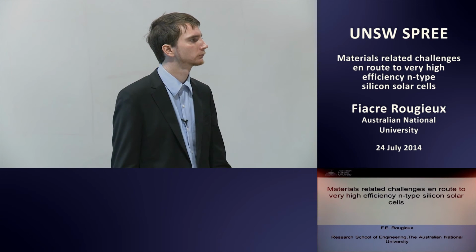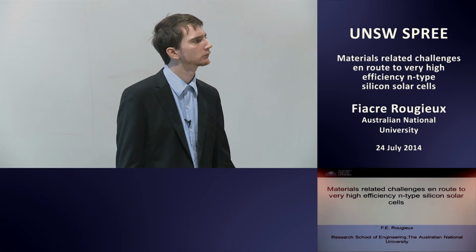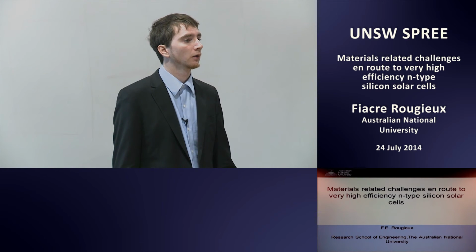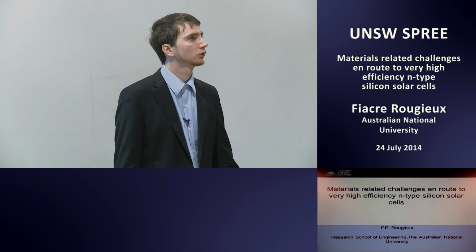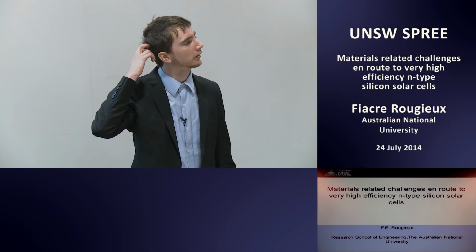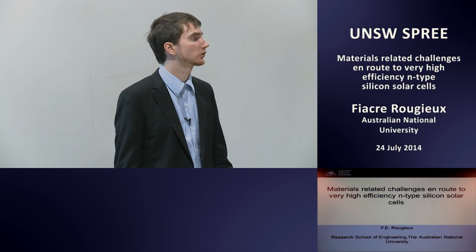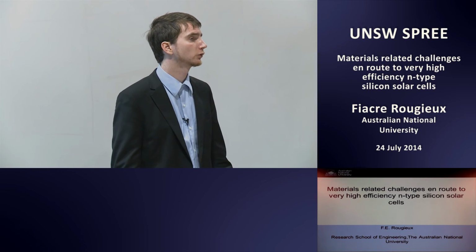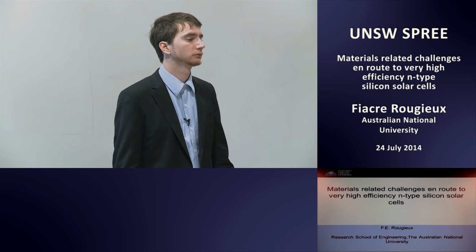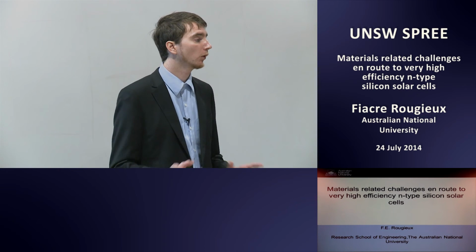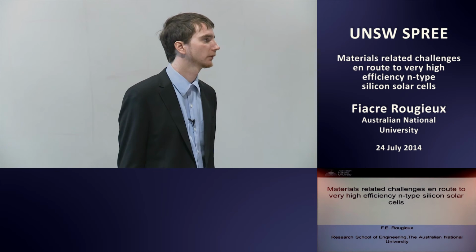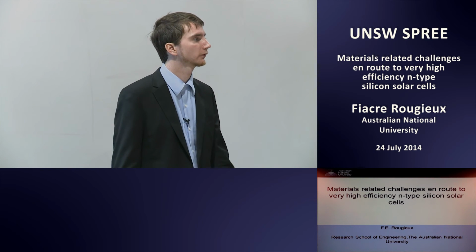So do you see the same improvements if you don't use nitrogen doping of the FZ? No, we don't see it, because it's already high lifetime. So we don't see an improvement for the non-nitrogen doped float zone silicon wafers. But we see all other funny effects with the non-nitrogen doped float zone silicon wafers.